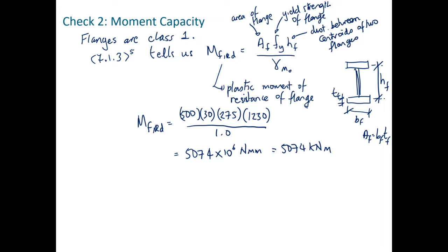So the demand MED is 5250 kilonewton meters, which is greater than the capacity of the flanges to withstand that bending moment.